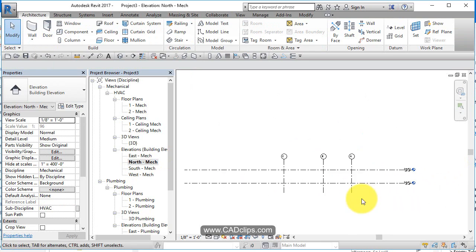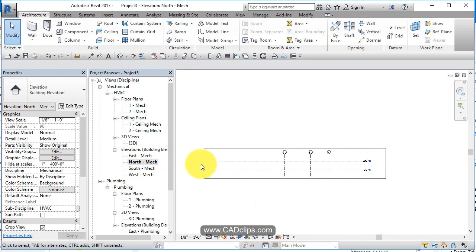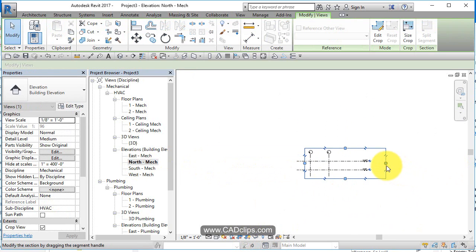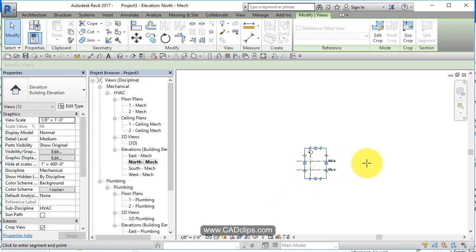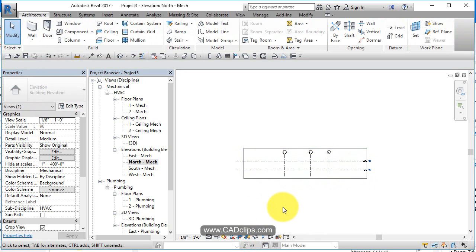Okay, the grid lines have to be within your view. If you go to your crop region, and your crop region you've turned on is being cropped down to here, it's only going to show you that one grid line. Okay, you have to make sure that your crop region is big enough that it would see the grid lines if they are there. Turn the crop region off.